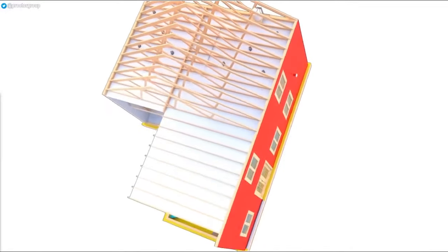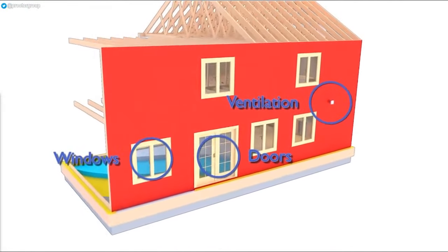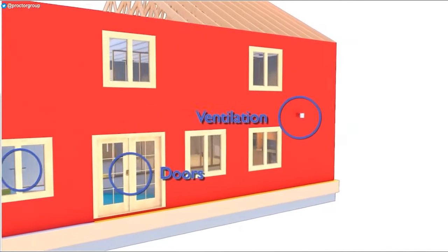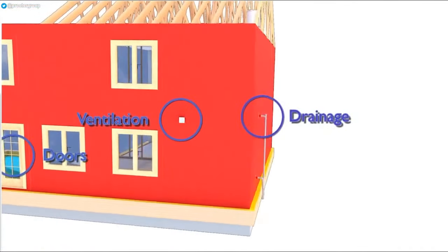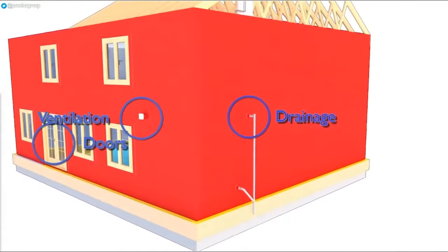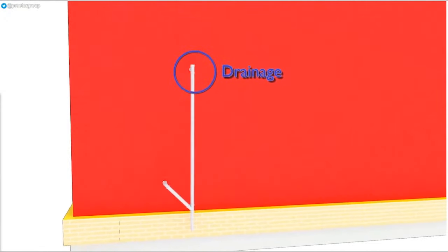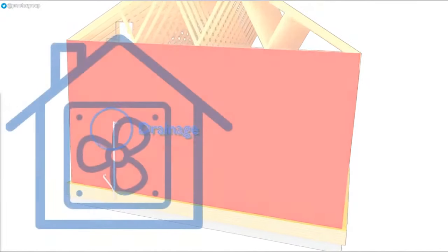External air barriers like wrap-tight offer excellent reliability and consistency. Window, door and pipe penetrations are made airtight in a straightforward manner with our wrap-tight tape or liquid flashing. This simplicity and reliability ensures the air leakage rate is more dependable and repeatable across buildings, which, as we've seen, gives significantly improved design flexibility in other areas such as thermal insulation.